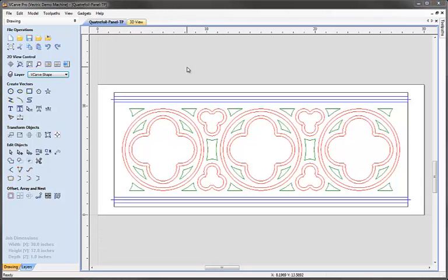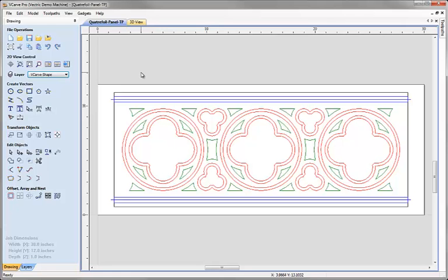This selection mode is important because it's normally the state that I want to get back to after I've been executing other functions. For instance, we'll now look at some of the tools we've got to navigate our way around the 2D view, but after each of these we really want to return to this selection mode. We can do that either by clicking on the arrow here or by hitting the escape key on the keyboard.